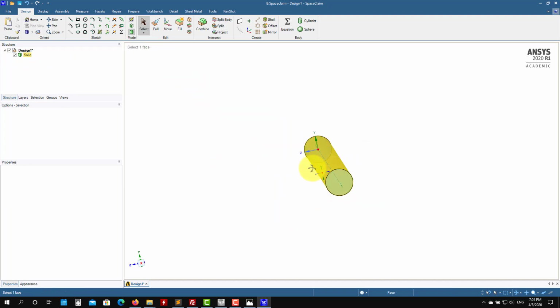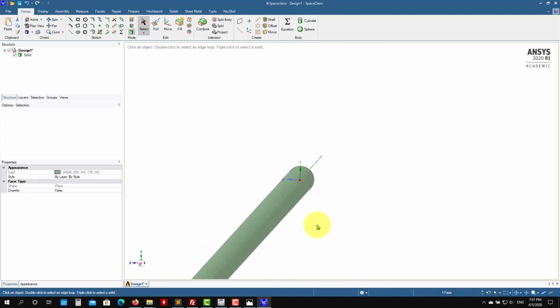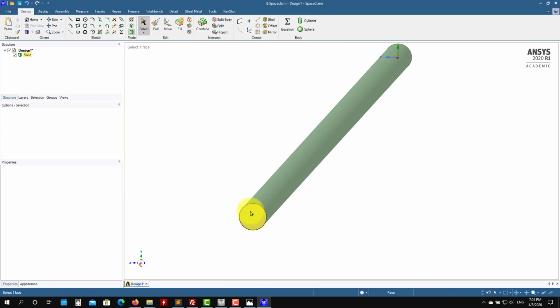And sometimes, also, here is a very simple geometry, you want to select some other faces. So see that, for instance, I want to select the back face, if I'm in this view. So sometimes you don't see that one. So what you can do is, you use the arrow up and see that it starts to select new ones. So let me put in this view here. And it goes to the other face. Or what you can do is hide faces. Okay, so right click.